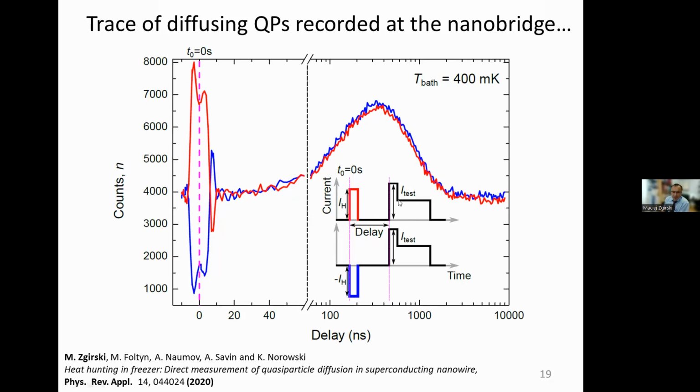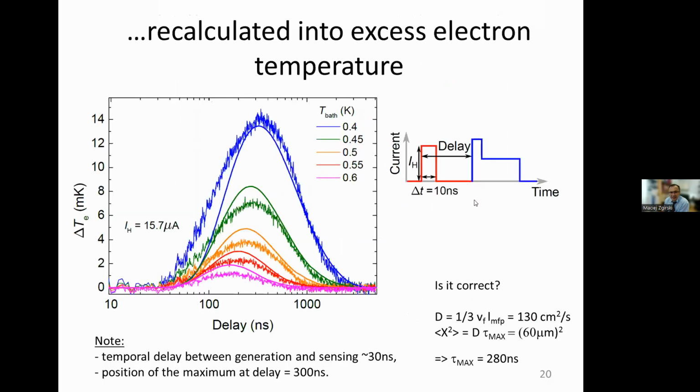Okay, so what is important is that when we invert polarity, you see that the crosstalk changes, but the thermal effect stays the same, meaning that this is really a thermal effect. It is not ringing, the signal is not sensitive to the polarity of the used pulse. We can recalculate this trace into temperature by using the calibration curve.